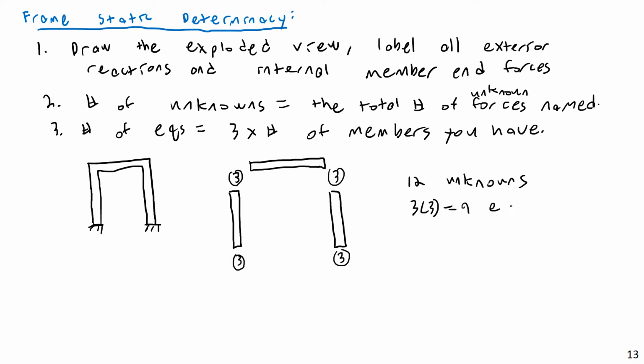And if we wanted to solve all this, we couldn't. We have 3 more unknowns than we do equations. So I would say this is statically indeterminate to the 3rd degree. This can be analyzed using some things from structural analysis, but we would not be able to solve it using the laws of statics alone. To the 3rd degree.